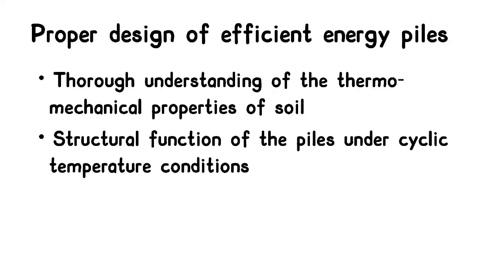That is, basically there can be a change in the pile resistance. So now, for proper design of efficient energy piles, a thorough understanding of the thermo-mechanical properties of soil should be known, as well as the structural function of the piles under cyclic temperature conditions should be studied in detail.